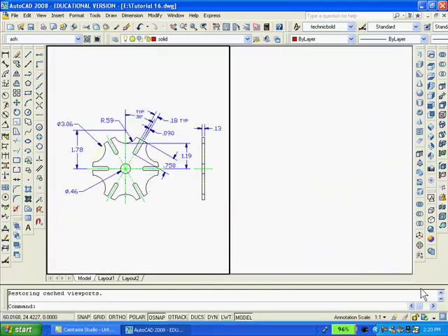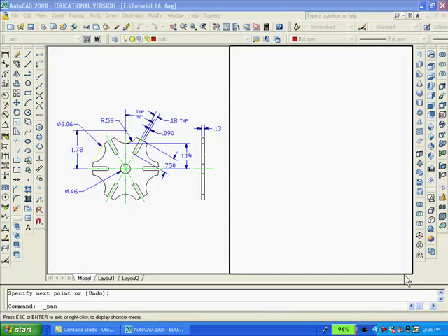Notice that the drawing still exists in Model Space even though erased in Paperspace, and that I split the screen into two vertical viewports so that there will be room to redraw the solid model on the right-hand side. I created the two viewports so that you can see the original drawing on the left and better understand how I'm going to create the solid model.